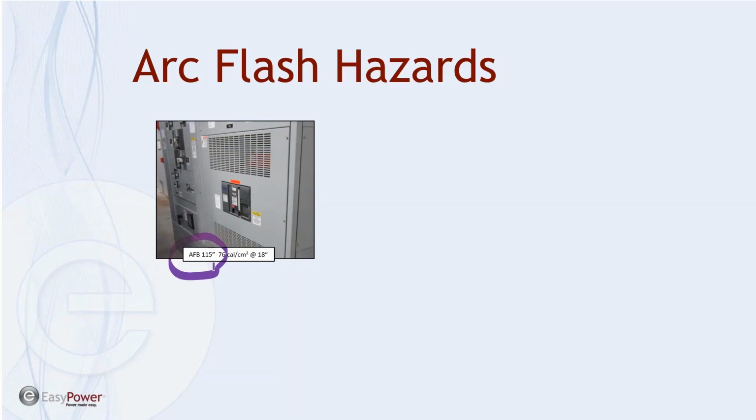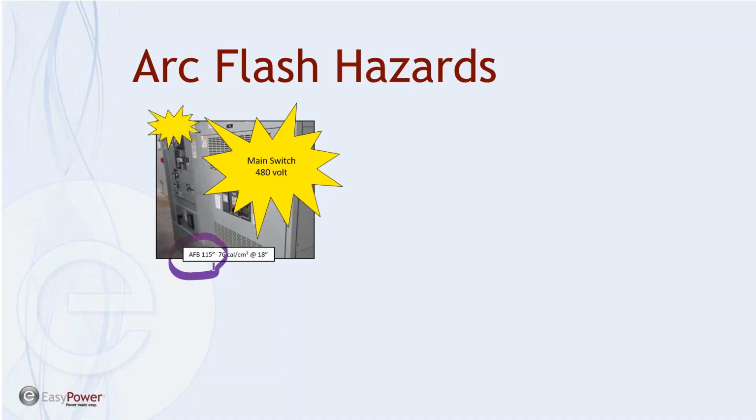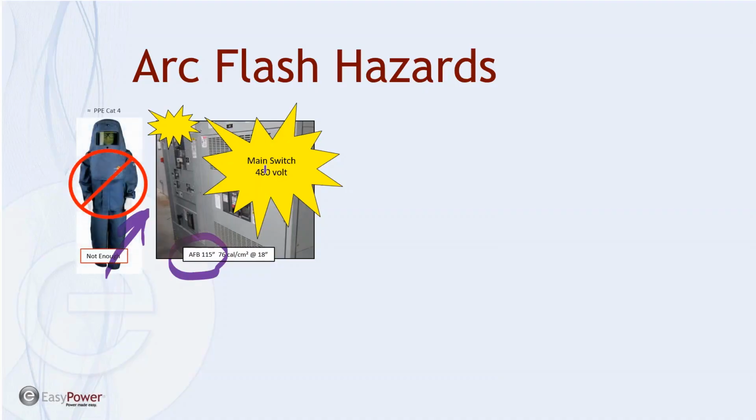So that's a pretty significant arc flash event that would occur. If it did occur, it would be significant, so we'd have to really consider what that is. Now, downstream from the main, where you have the main distribution panel, it would be lower, but you still would have to protect for the entire plant, the entire panel, at that same high level. So in other words, this is not enough. A category 4 is just not enough to be able to do that.